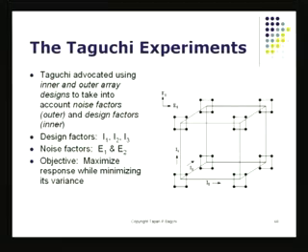When it came to doing the design using 2 factors, here I've got 2 factors. These 2 environmental factors are E1 and E2. The way Taguchi combined it, he said, bring in not only your design factors to do a robust design set of experiments, but you've got to also bring in these environmental factors, or what we call noise factors. For that, you have to select the settings for these noise factors.